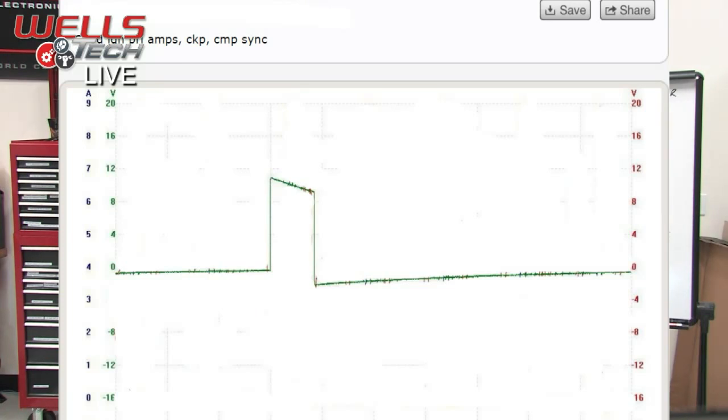One being, we know that this is a digital sensor. So a digital sensor is a low to a high back to the low. It should be a square wave. Yeah, that is correct. You can see here that that's not a square. Somewhere we're losing the power, or our ground is not right. It's the ground that's wrong here. And you can see that when it comes across the top and comes back down, it goes lower than what our ground value is.